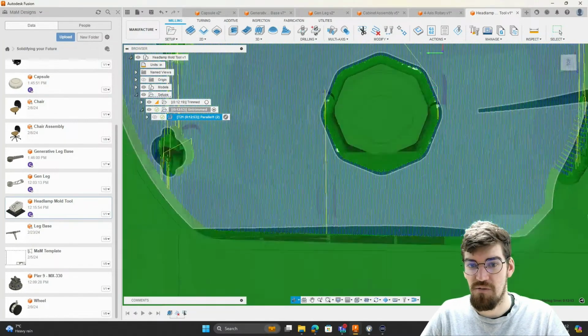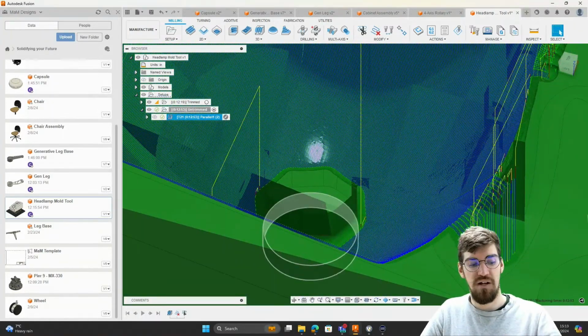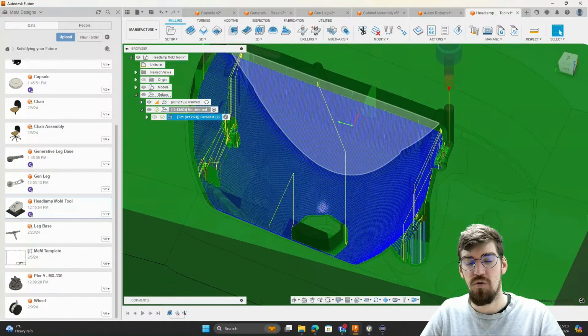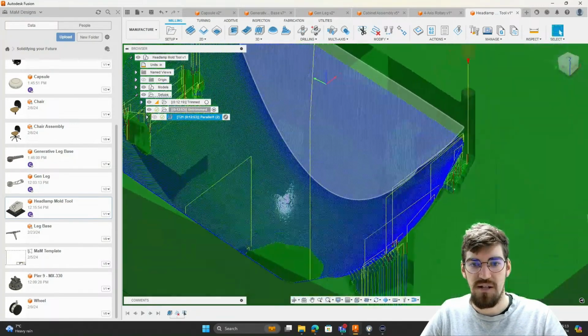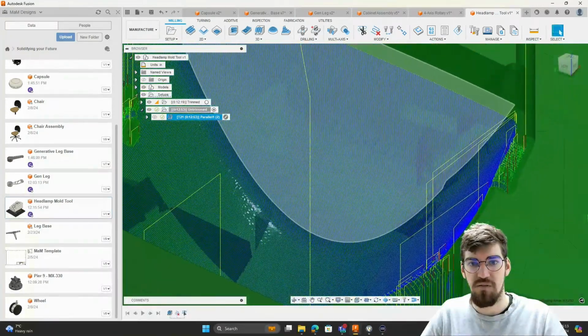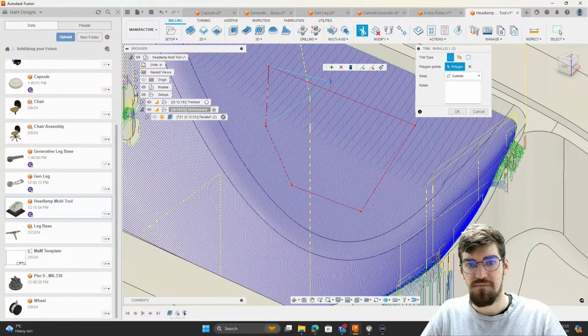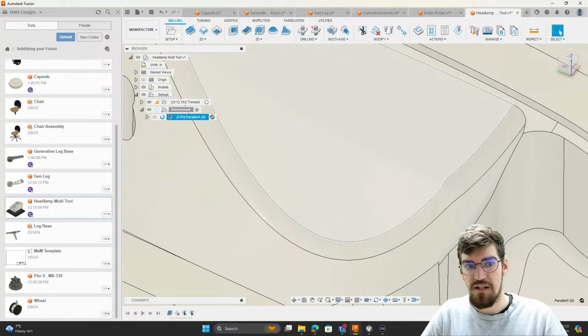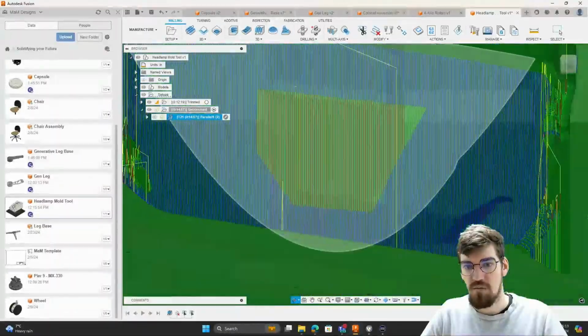But if I decide I want to go from a very particular angle, there might be an angle that isn't accessible by your component itself, your machine itself, if you aren't using machine avoidance and all of that, we could say, well, actually from this particular angle over here, let's remove the toolpath, anything that sits within this region over there. And it'll then remove anything that sits within that region and not make contact with that surface there.